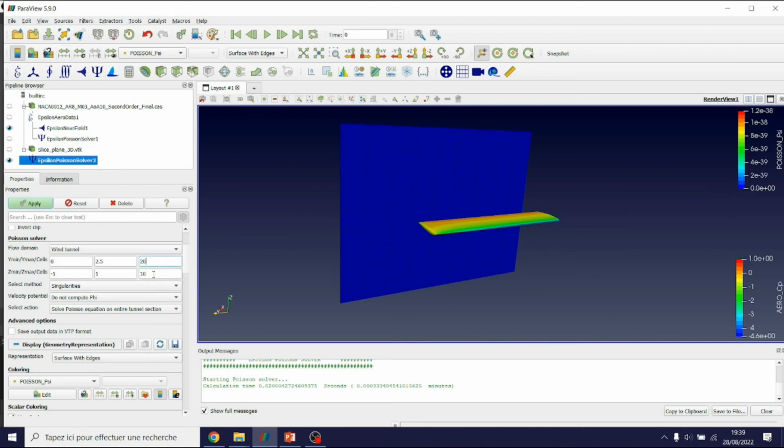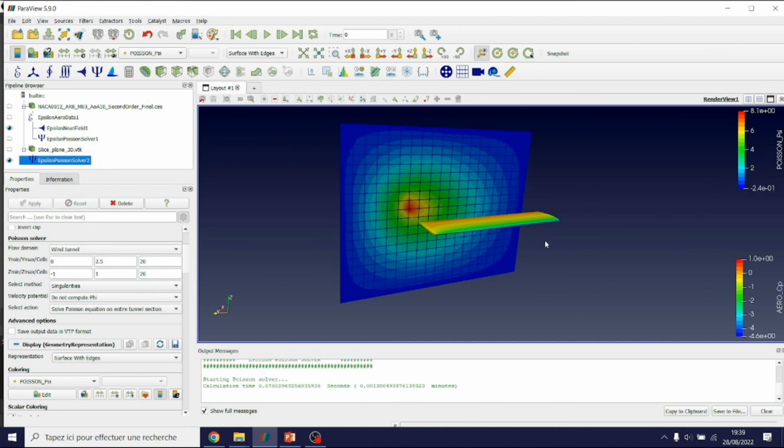You may increase that a little bit more and try it. Yes. As you can see, I use a coarse baseline mesh just to make sure that the constant values of the stream function actually follow the wall, the boundaries. This means that the number of panels that I'm using here is enough to ensure that the streamline very, very close to the wall actually follows the wall. You will see that this contour line, as it gets closer to the wall, will follow the surface better and better. Of course, if my baseline mesh is coarse, it will not follow it as well.